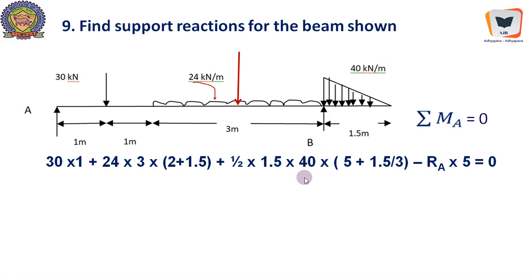Therefore meter will cancel away, and we will be getting 60, that is 20 into 1.5, that is 30 kilonewton here, acting at a distance of 1/3 of base, 1/3 of 1.5 meter, or 2/3 from this apex, or 1/3 from here. So 1/3 of 1.5 is 0.5 meter.